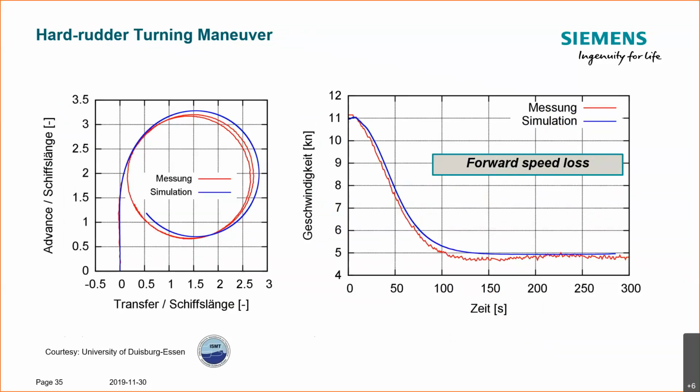And I throw this at the audience right off the gate because it underscores that the direct simulation of maneuvering based on RANS equations is the best known model and has the least risk of not meeting the accuracy requirements when we compare to measurements, if the field sea trials were done correctly.